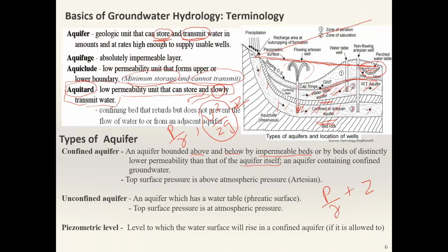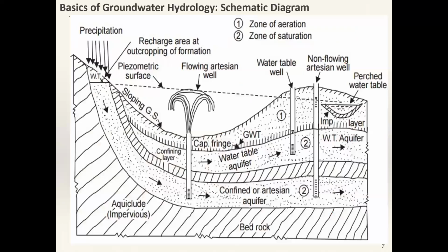When water flows through a pipe, because of the friction effect, there is a head loss. So similarly, when water goes through the porous medium, there is a head loss. That is why this piezometric head level decreases in the direction of the water flow, right? Okay. So again, this is the same discussion about confined and unconfined aquifers, then the perched aquifer, and piezometric head, right?